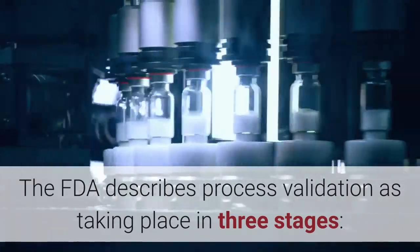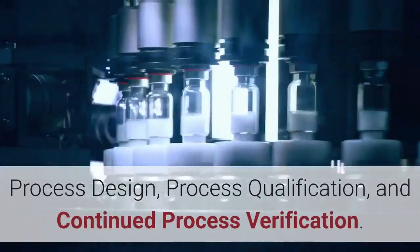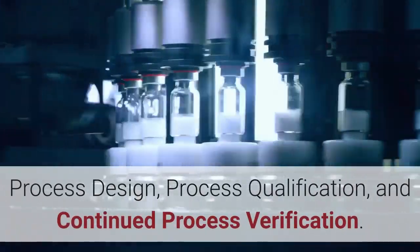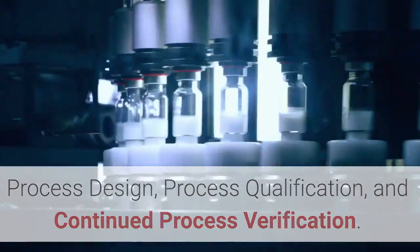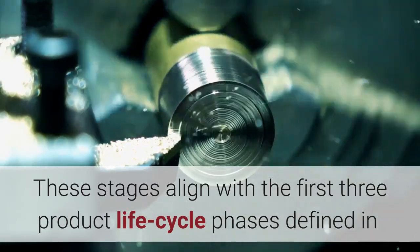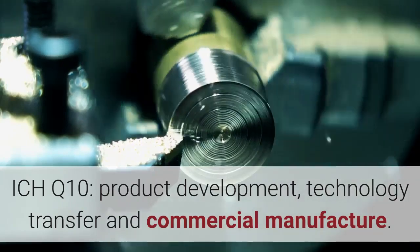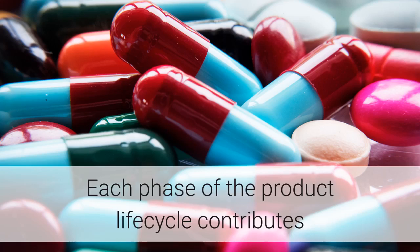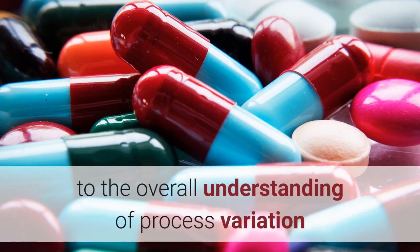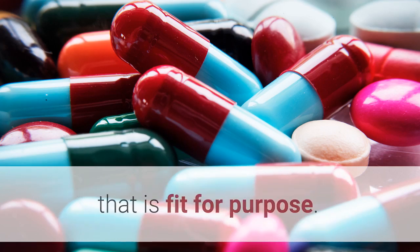The FDA describes process validation as taking place in 3 stages: process design, process qualification, and continued process verification. These stages align with the first 3 product lifecycle phases defined in ICH Q10: product development, technology transfer, and commercial manufacture. Each phase of the product lifecycle contributes to the overall understanding of process variation and control of the manufacturing process to deliver a drug product that is fit for purpose.